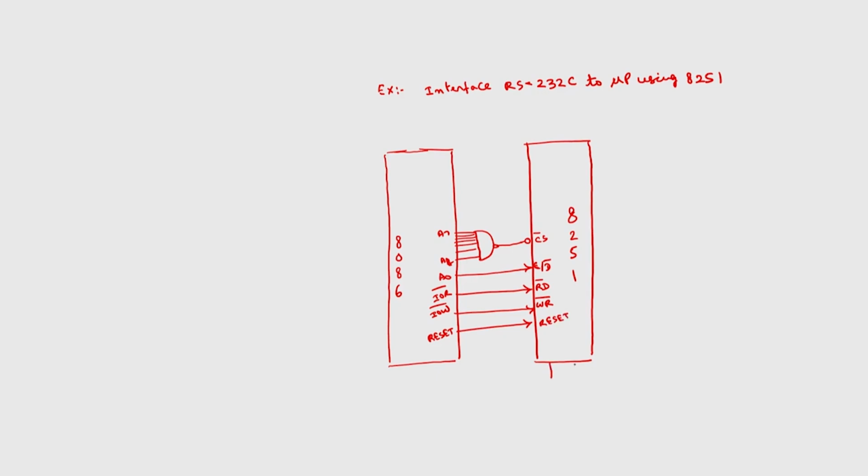Clear to send bar, whenever it is ready, should be 0, so I will connect it to the ground point. On the other side we have the serial data that can be transmitted.